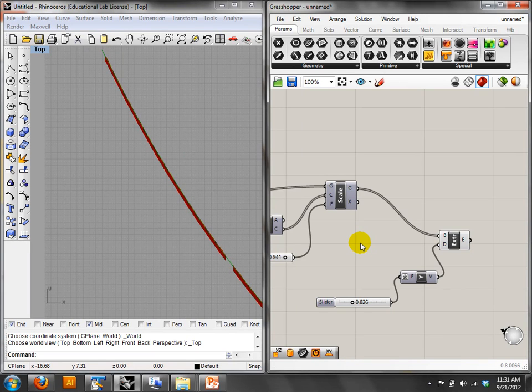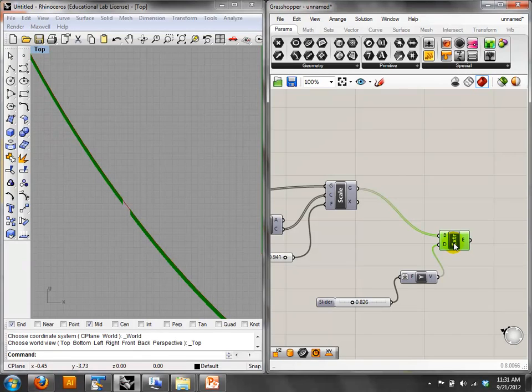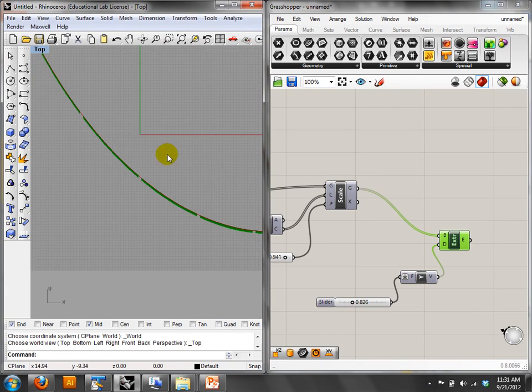Evaluate, yeah. You do an evaluate surface and a curve on surface point, or the closest point on a surface. And that's actually going to give you the vector for each one of these panels, no matter which alignment it is, and then you feed those alignments into it for the extrude, and this will work for anything. So you'll get this checkerboard pattern on a sphere if you want to, because it's going to use the normals locally. Okay, so good. So that's the kind of idea.